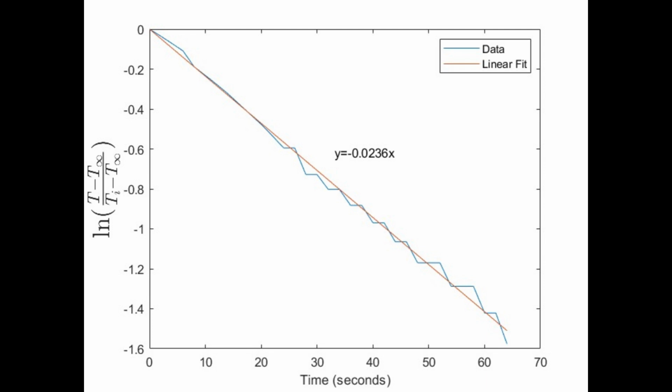As seen from the graph, the data should have been in a straight line, but towards the end, and a little in the beginning, there are periods where the temperature stays the same for a long period of time, indicating how the probe lags behind. This definitely affected the slope predicted by the model, which in turn affects the calculated convection heat transfer coefficient.